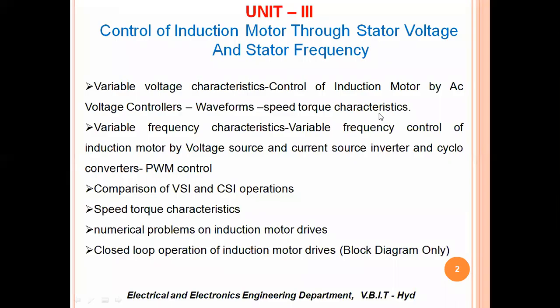Right? And now coming to the induction motors, three-phase induction motors are generally classified into two types. You know them. One is the squirrel cage induction motor, and the second one is the wound rotor induction motor. The wound rotor induction motor is also called a slip ring induction motor. And based on their construction, the names have been given as squirrel cage as well as slip rings, wound rotor or slip rings.